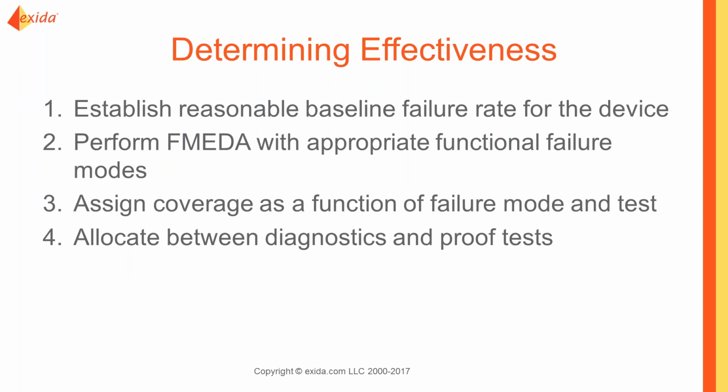of a device. We need to perform an FMEDA on that device with appropriate functional failure modes. So when we're doing SIL verification, we're often looking at, well, is it a safe or a dangerous failure? Is it detectable or undetectable? And that's important. When we're trying to evaluate the effectiveness of a proof test, we want to also consider from a functional perspective, if I get a failure, how does that present itself at a system level or a subsystem